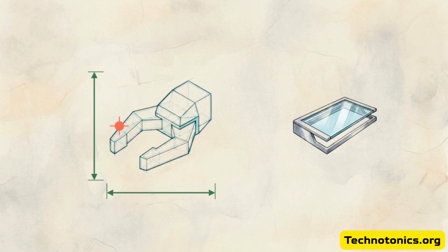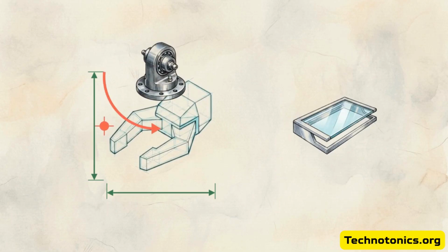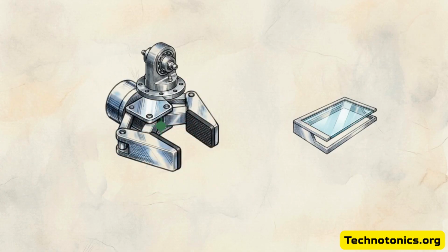Notice what happens when the center of gravity is offset. That shift alters the torque applied to the robot's joints, changing both its physical reach and its movement physics. When you accurately input these metrics into RoboDK, the payload warnings disappear. Your 3D viewer is now perfectly aligned with the real-world end effector.